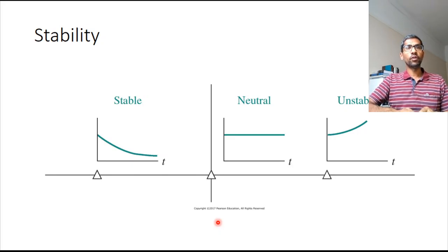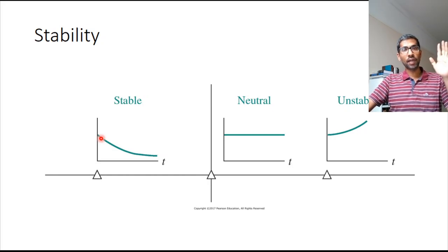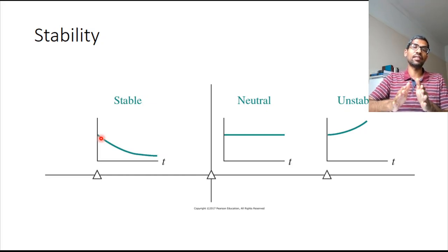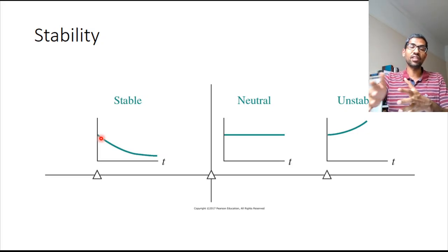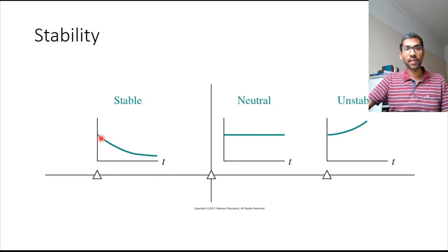So in all our solutions to figuring out whether a system is stable or not, we are going to do the very simple thing of trying to find out the poles of the system. And if the real parts of the poles are negative, great, our system is stable. Otherwise, even if one of the poles does not have a negative real part, or it has a positive real part, then the system is going to be unstable.